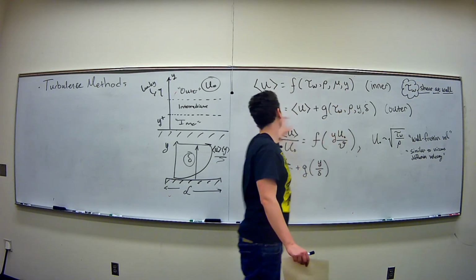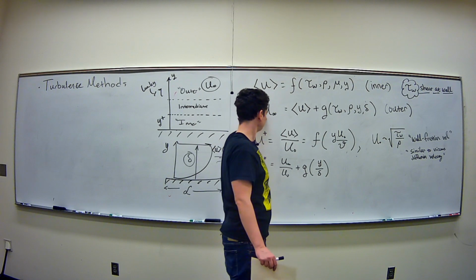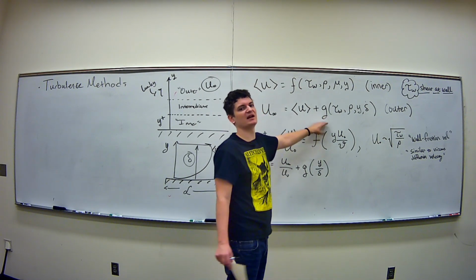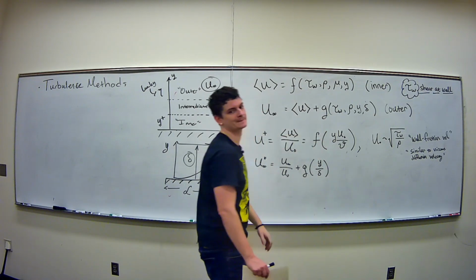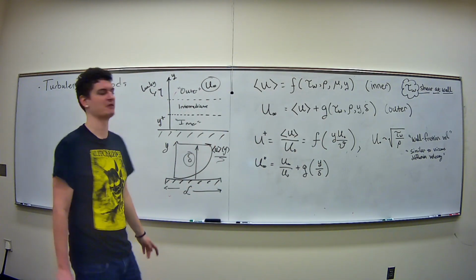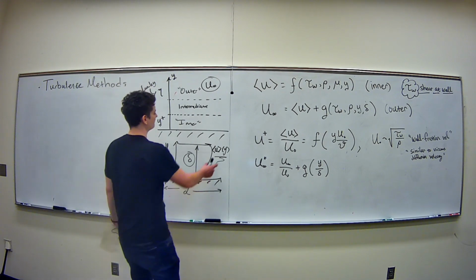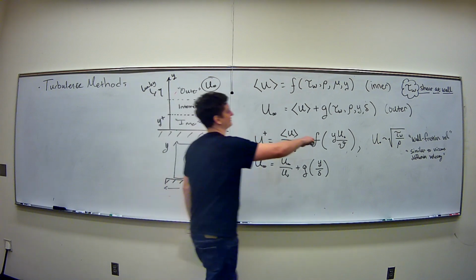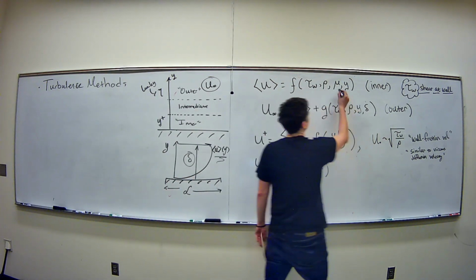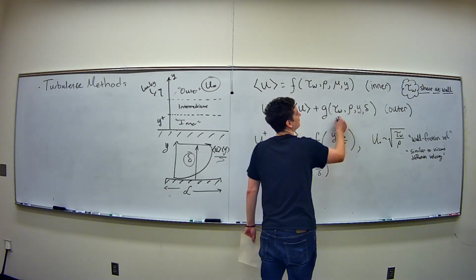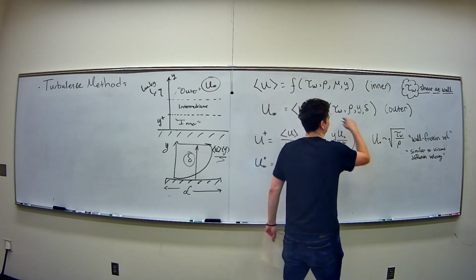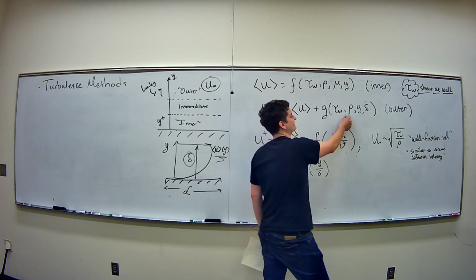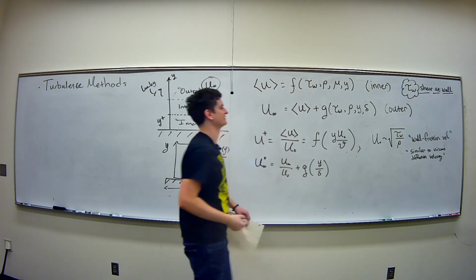And now for my outer region, right, the outer flow is going to be that mean flow plus some term. It can fluctuate as well, right? If I'm above this mean flow and it maybe is going crazy and wild, whatever's around it would also look like that as well. The only difference being I'm far enough away from viscosity that it doesn't matter anymore. All that matters is really this turbulent shear stress that's going to move the mean flow around. So that's going to be here. And then density still matters because the mass is resisting motion.